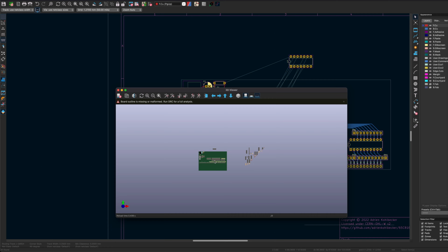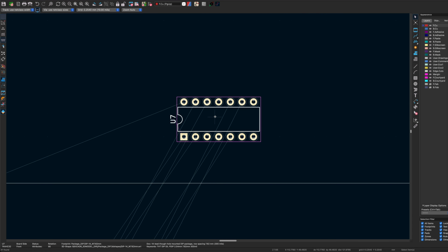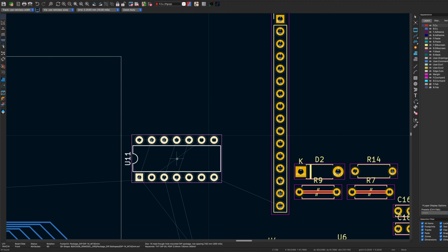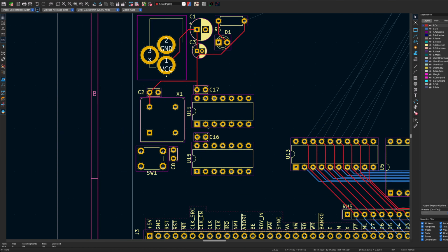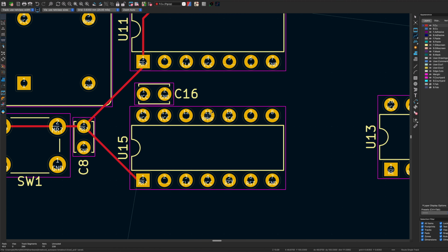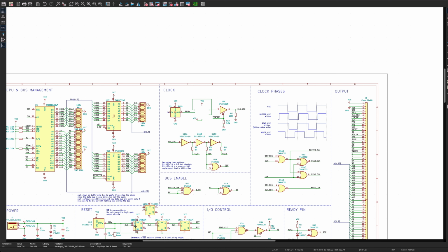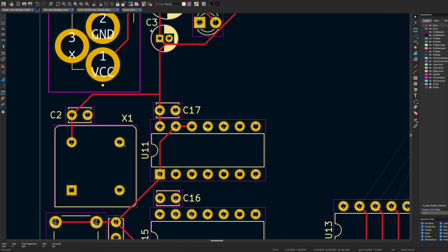Let's see what it looks like in the 3D viewer. Looks good for now. So this is bank 0. I'll do that later. Let me first work on the resets. So here is the 8 MHz signal. I would like this on the top flip-flop, so I have to invert it between 15 and 11. Okay, so 15B, I switch with 11B. Let's update the PCB. Okay, then I can take it directly from here.